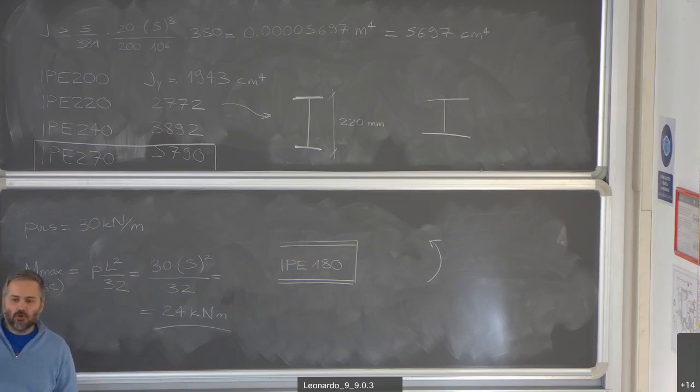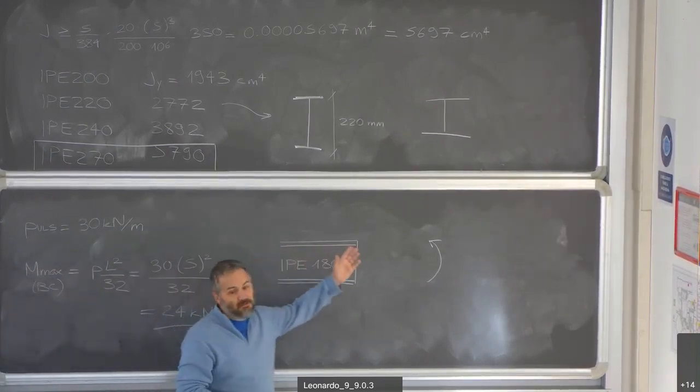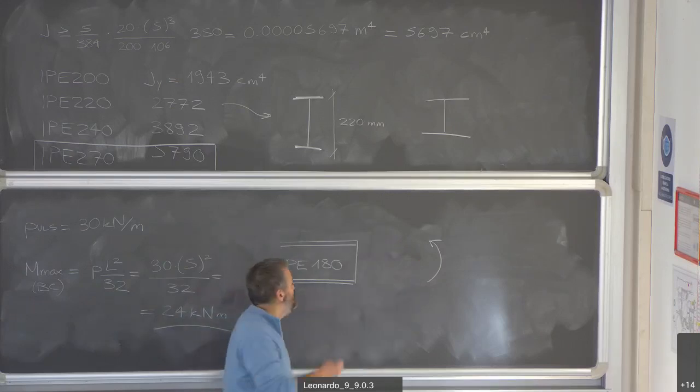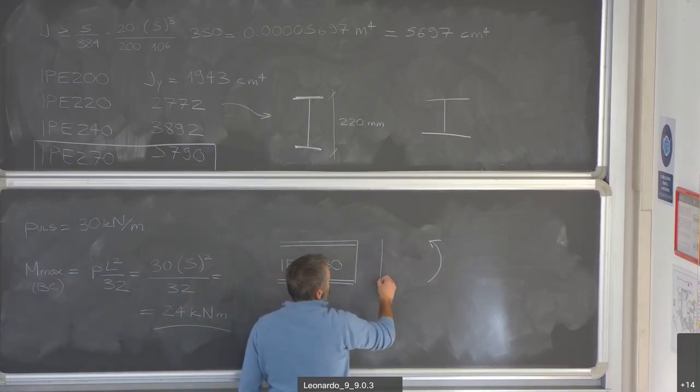Go back to the notes when we talked about bending capacity. You remember there is this phenomenon called redistribution. So starting from a linear distribution of stresses, we redistribute up to the point where all the fibers are working at their maximum stress, which is the yield strength, with a distribution that has to comply with the fact that we are talking about bending.